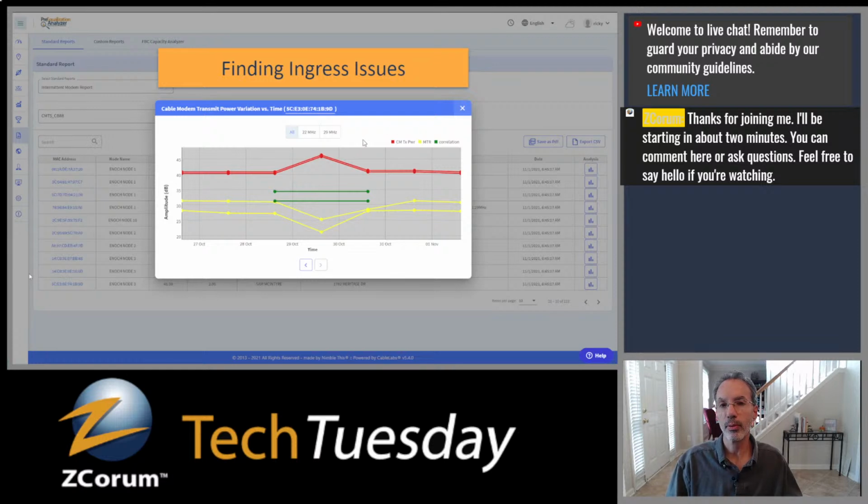At the same time, it's adjusting its cable modem transmit power. So we go, you know what, this device seems to be reacting to ingress, to some noise that's coming in very nearby that device. So it tells us this particular device probably has an in-home or near-home issue, something that's letting noise in at specific times, not all of the time.